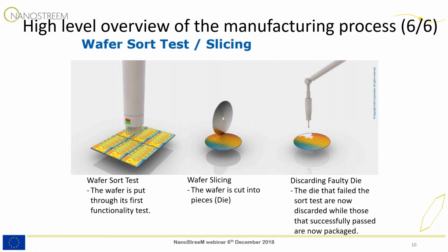And at that stage, we hold on to the die that pass all the functional testing, and the ones that do pass, we basically process further in different facilities in order to package them, and it becomes the product that you'd be pretty familiar with. So as I say, that area of polishing is one of the key areas when it comes to our use of nanomaterials.